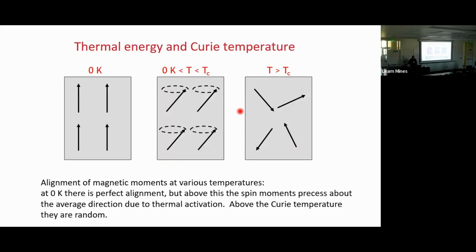So there is a particular critical point, although it's not exactly a point. There is a little range in which, before and after this range, you completely lose your magnetic moment. It's not a single point, but for ease of comparison, instead of giving a range and confusing people, what people do is take a derivative of the magnetization versus temperature, find the point of the steepest derivative, and pick that as the Curie point.